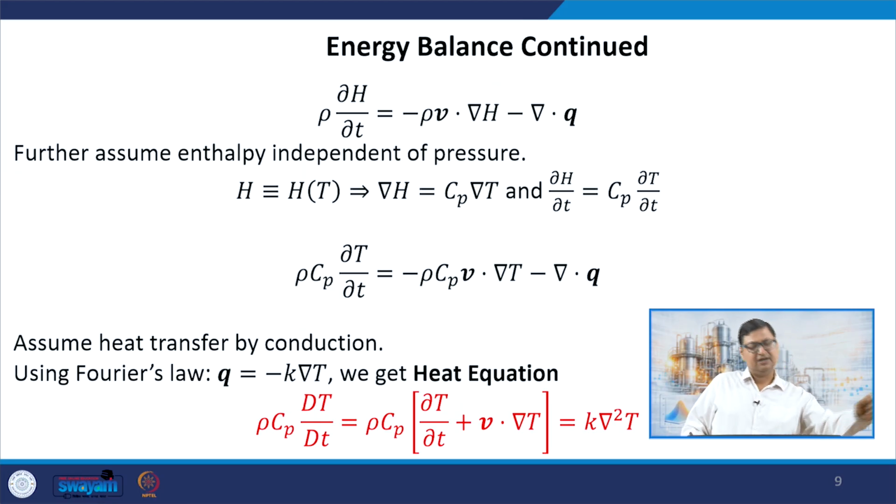Going forward, I am going to use the notion that enthalpy in principle can be dependent on pressure, but we can ignore it for most liquid systems. And the enthalpy can change because of either a sensible heat change, that is something like Cp delta T kind of change, or as a phase change, that is latent heat change. In most cases, we are interested in only the sensible heat change, right?